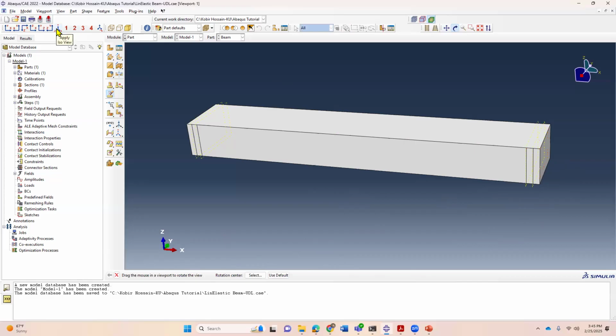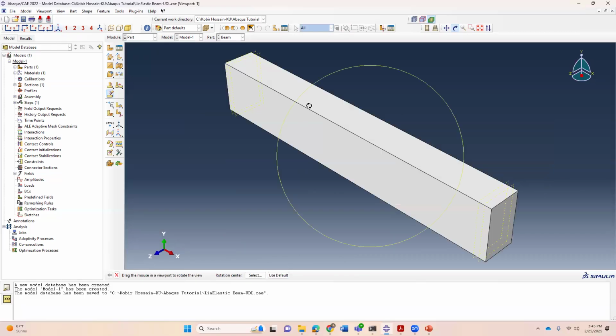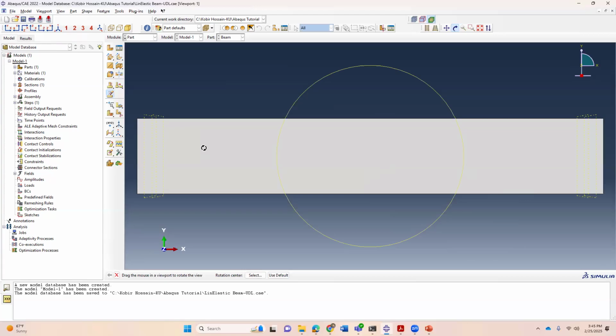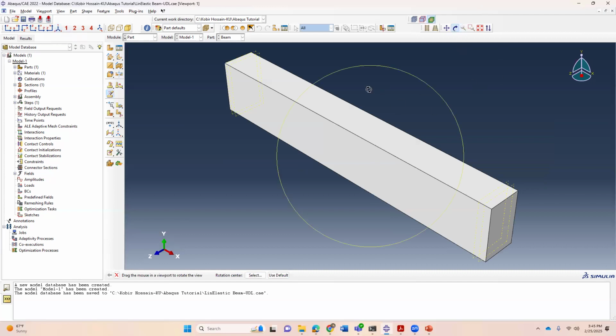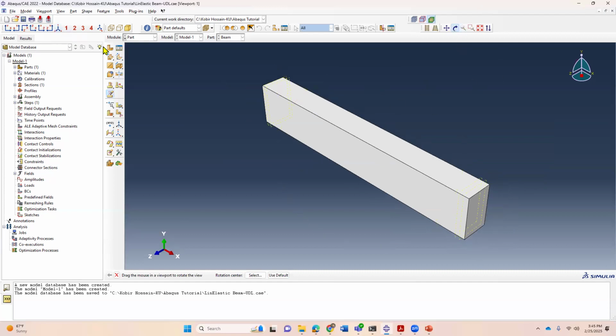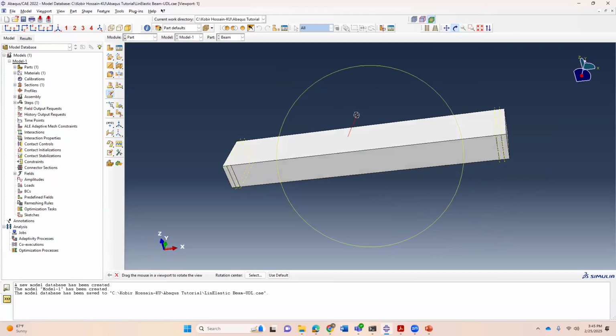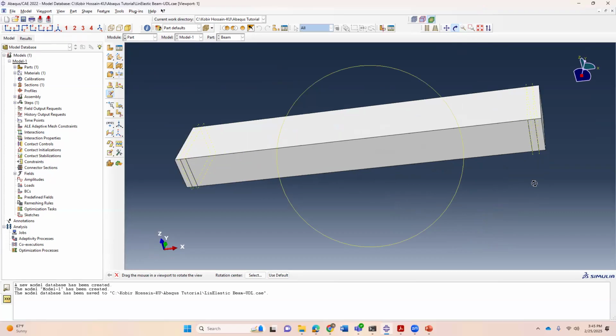So for the 3D view, we click on apply isometric view, this option. To see XY view, the front face, we click on XY face. We have 7 view options here, and we also have a rotate view option too. So now what we will do, I think I need to partition this face a bit more. Sorry, I'm taking long, but I think it will help you learn step by step. Sometimes we make mistakes, and how can we come back from there? So we need to learn a lot.